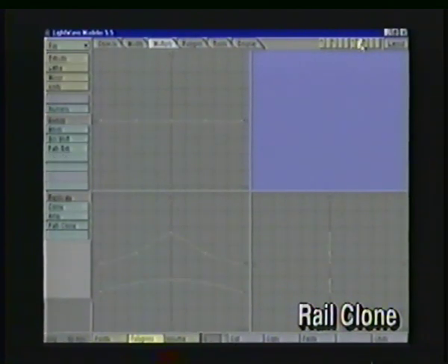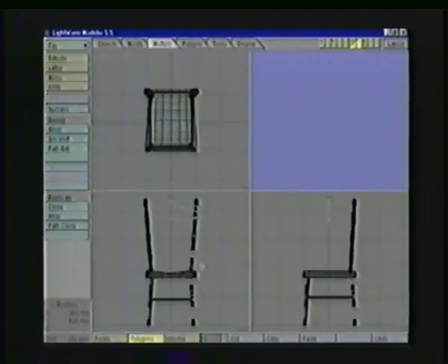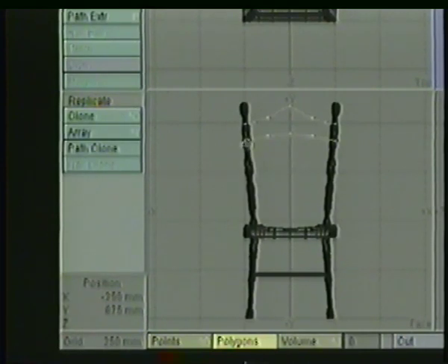So I'm going to go to the area with my curves. I'm going to put my chair in the background. I'll hit A to fit all my views. And what I want to have is the top of the rails pretty much matching the bottom of my back piece. So I'm going to leave that curve where it is, select the top curve, and I want to shift that one straight down here to the bottom, and I want it to be fairly flat along the bottom so the posts sink into the base of the chair.